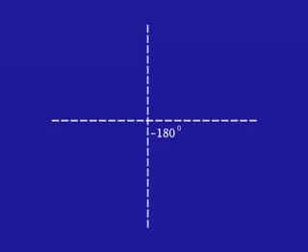Now, think of again two axes, but now along one axis what we have is angle or phase shift if you wish, and along the other axis we have what is gain, either absolute gain or gain in decibels. Now, it turns out, and we will see the reason for that very soon, that the phase shift variation usually will have minus 180 degrees as the central point, and then it will range towards one direction of increasing phase shift and another direction of decreasing phase shift.